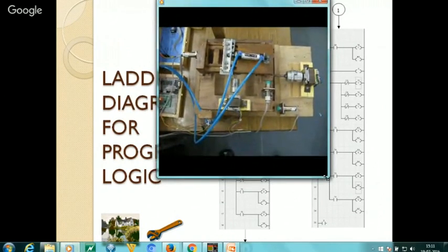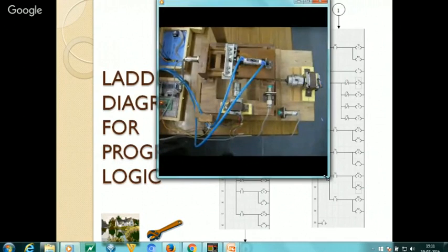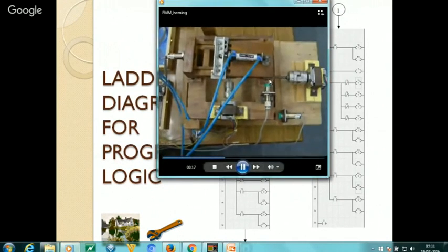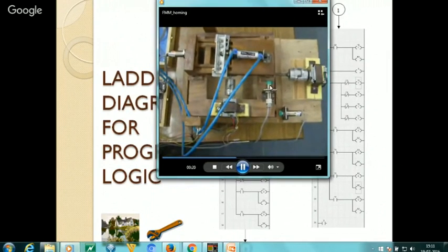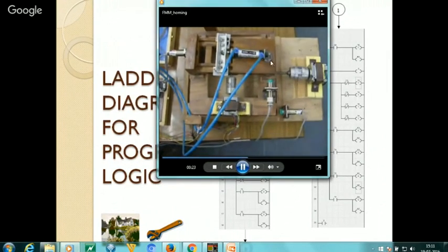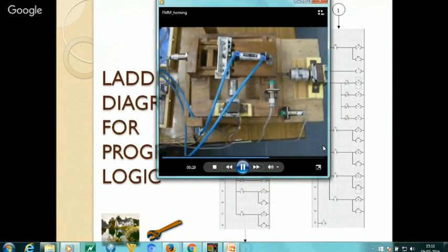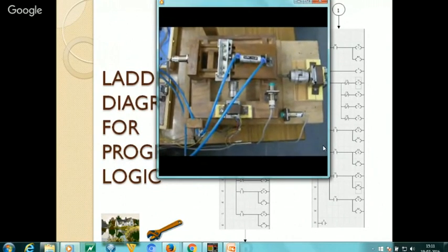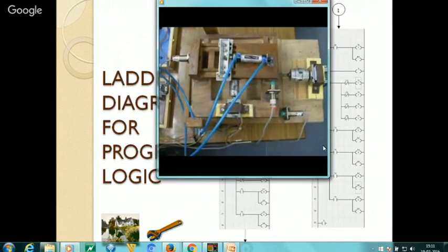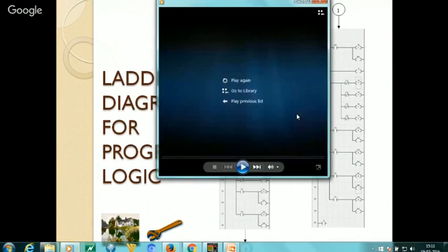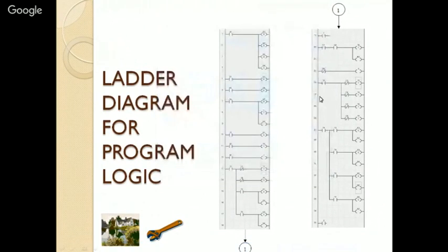Now in this mode, the stepper motors are run continuously. When these sensors detect the 0 position, the stepper motors will stop. This one is of the upper slide and this one of the lower slide. So as these two give a signal to the controller, the motors are stopped. This is about the starting.